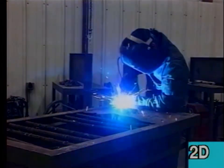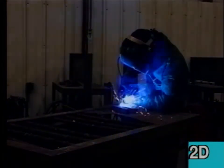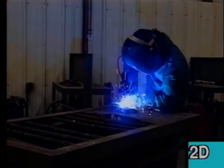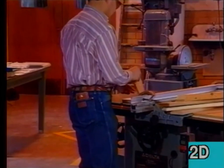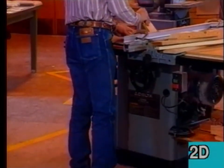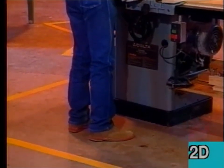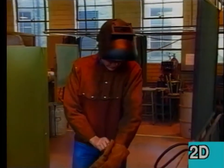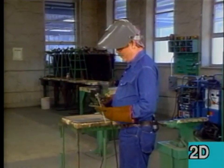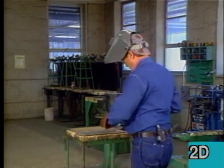Now that we've properly protected the eyes, face, and ears, what about the rest of your body? Protection from injury also means wearing the proper clothing. Students must wear clothing that is appropriate for the work being done. In general, long-sleeve shirts with cuffs buttoned, long trousers, and closed-toe shoes should be worn. For welding, clothing should be flame-resistant. Clothing made of natural fibers such as wool or cotton provide better protection than synthetic fibers like polyester.